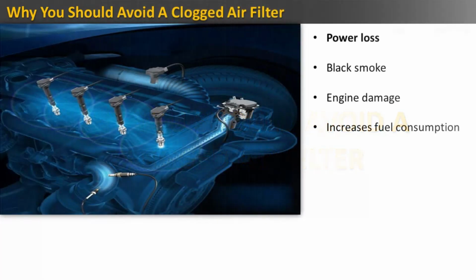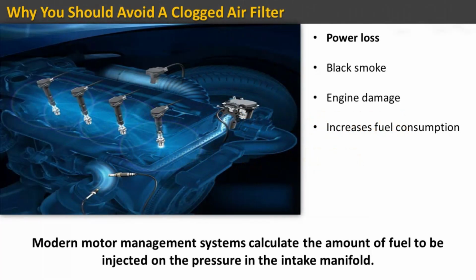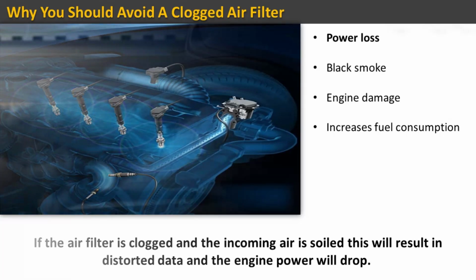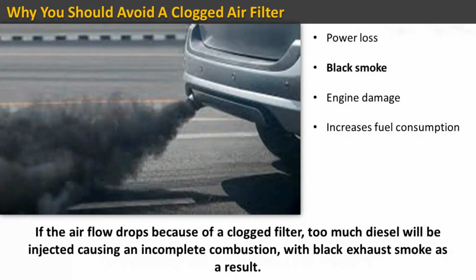Power loss. Modern motor management systems calculate the amount of fuel to be injected based on the pressure in the intake manifold. If the air filter is clogged and the incoming air is soiled, this will result in distorted data and the engine power will drop. Black smoke. If the airflow drops because of a clogged filter, too much diesel will be injected, causing an incomplete combustion, with black exhaust smoke as a result.